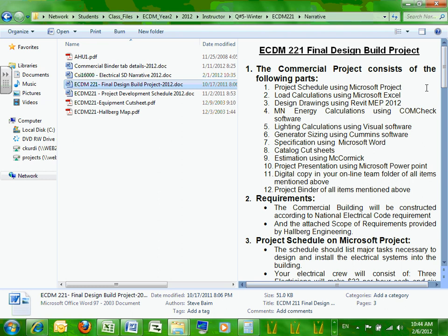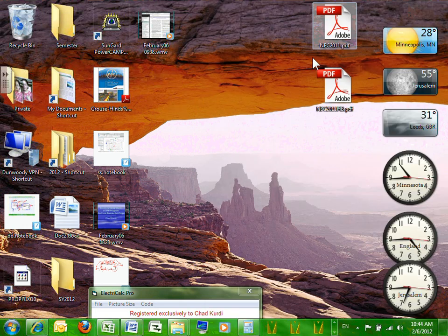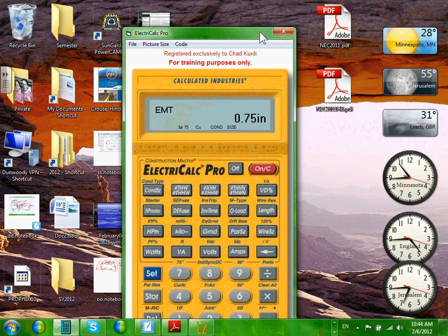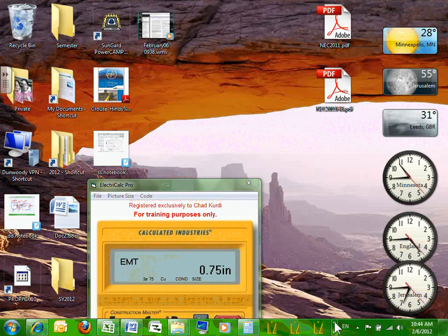Is there a reason it should be drawn in CAD as opposed to Revit? No reason. Be my guest and do a drafting view and draw them in Revit too. You have to have a drafting view. No reason, other than CAD will allow you, we're still CAD. Remember that detail line, and you go right there.